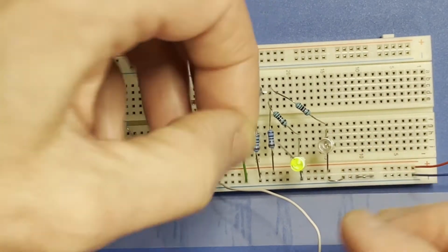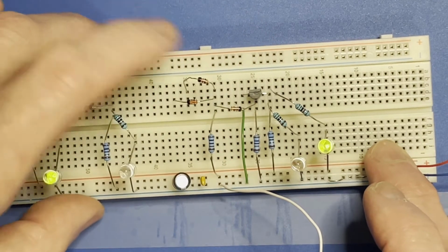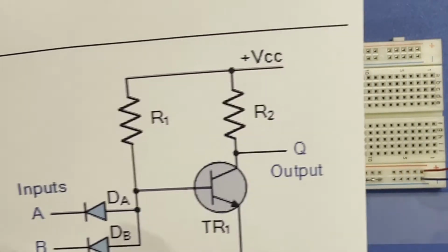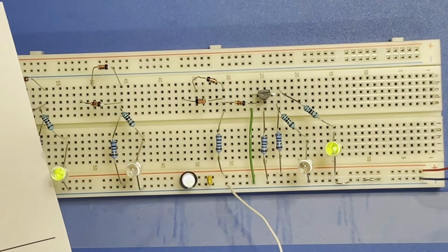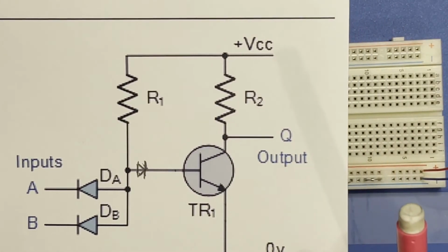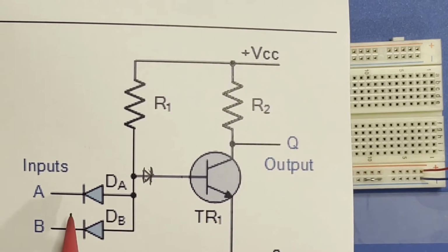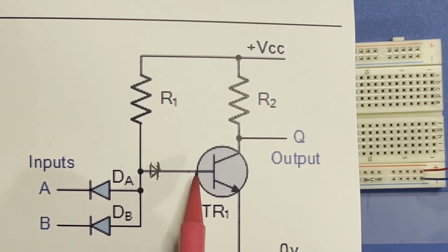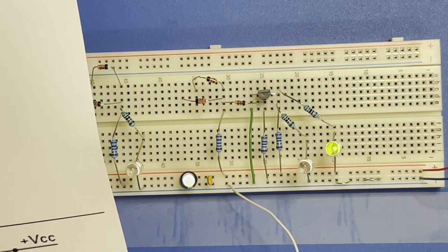There. You can see that's turned back on again. What I've done at that point there, I have added another diode. So now, when the input is pulled to ground, let's start again. I have also got a resistor there.